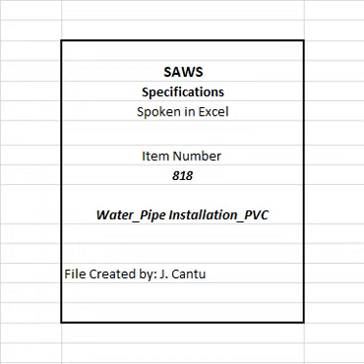9. Tracer wire shall be utilized for location and taped directly to the pipe. A. Tracer wire shall be properly spliced at each end connection and each service connection. B. Tracer wire shall be adequately wrapped and protected at each splice location in accordance with manufacturer recommendations. C. No bare tracer wire shall be accepted.